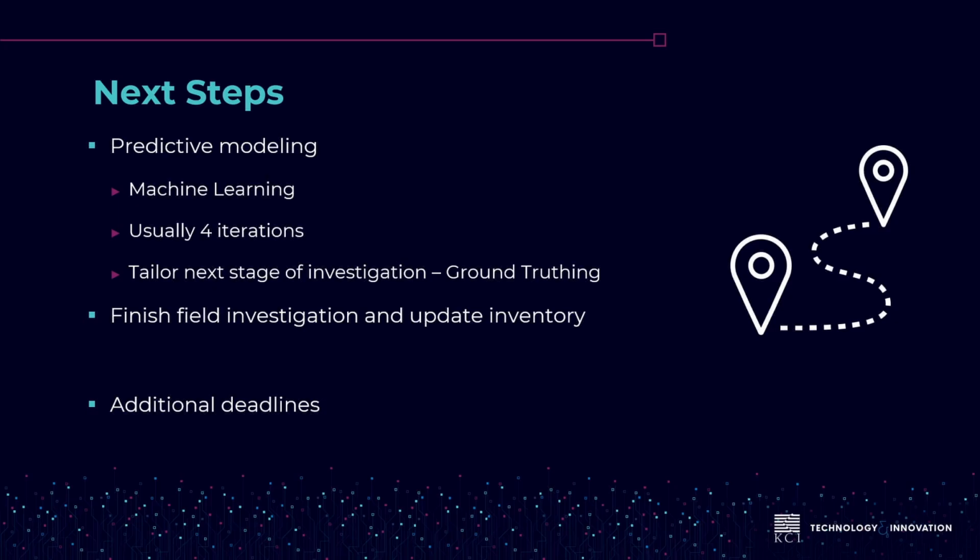And as you may be aware with the LCRR, LCRI, there are additional deadlines moving forward if nothing changes that include the baseline inventory for things like the connectors by 2027, replacement plans by 2027, and then verification of non-lead pipes by 2034, and then complete replacement of any lead or galvanized needing replacement by 2037.